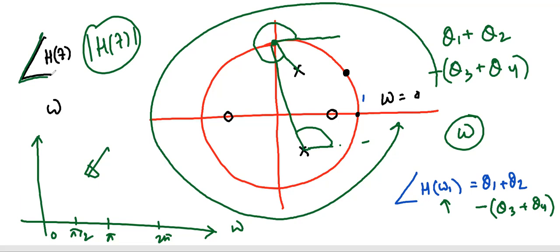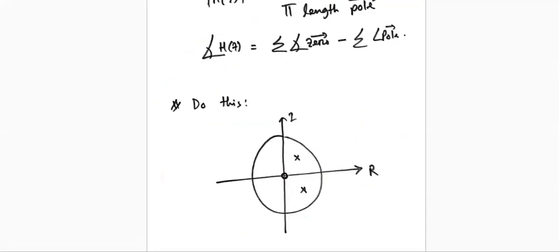So this is very simple, how to deal with the magnitude response as well as the phase response from the z-plane. And I need to be very specific that the magnitude response, and mostly the phase response, is only true when all the poles and the zeros are inside the unit circle.